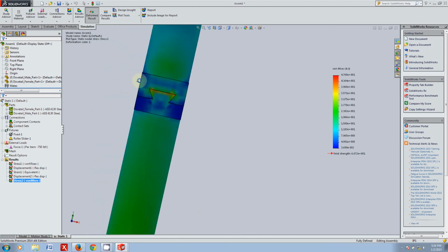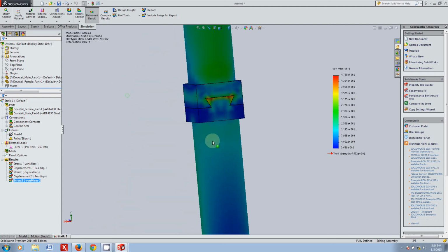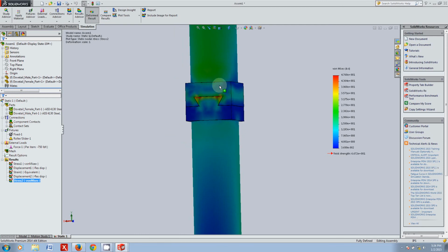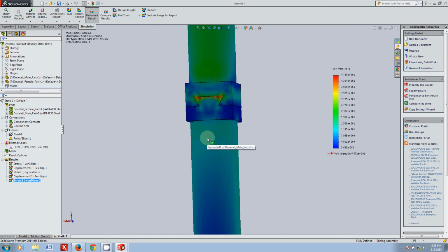You could even go back and redesign it so you get a little bit closer and have a slightly smaller factor of safety. You could try a bunch of different material removal techniques to remove material and hopefully improve the efficiency. But more or less, as long as it says that you're not yielding the material, then you probably should be okay. You definitely don't want your material to yield. Unfortunately, there aren't any fracture models included within SolidWorks by default. Fracture is actually an ongoing topic of research in the realm of finite elements, but it still gives you a reasonably good idea. As long as it's not yielding, you should be fine.